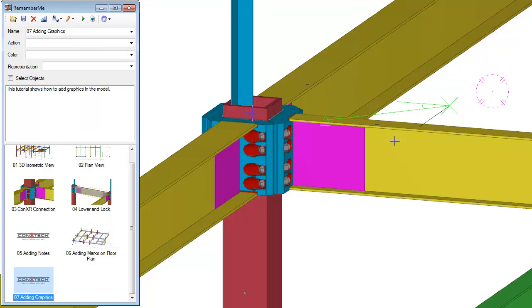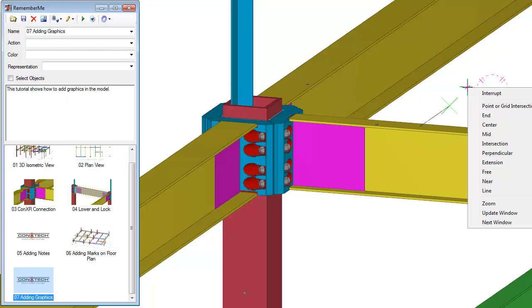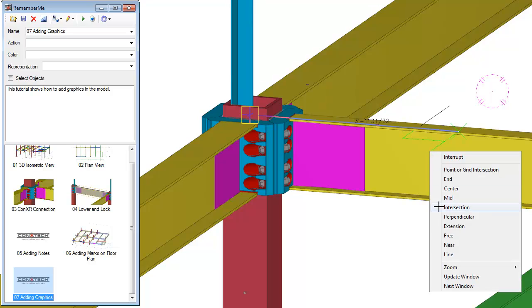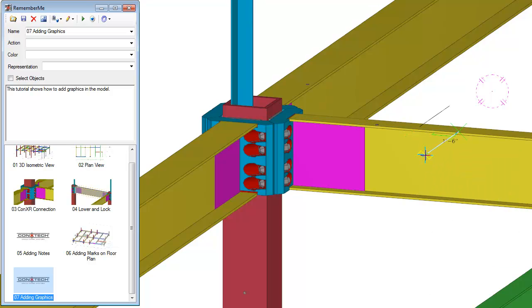Let's do the single arrow functionality. The first point that you select here is always going to be the head of that particular arrow. So we'll select here, and let's go in the opposite direction this time. We'll say snap to free, and there you can see the arrow has been drawn. The arrow is always drawn in both directions, so no matter what view you're currently in, whether a true 2D plan view or elevation or a 3D view, you can easily see that arrow or graphic.